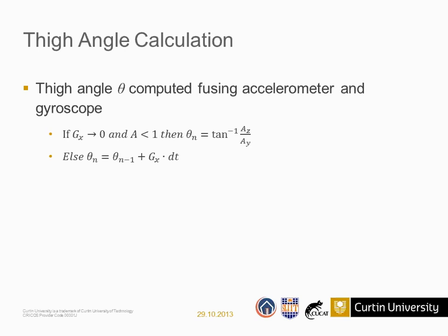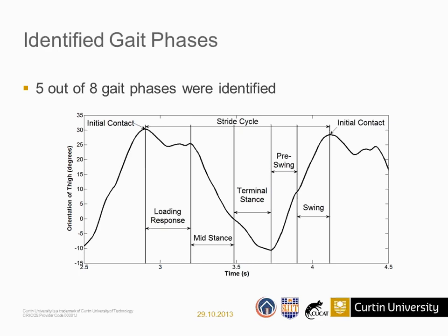So what I did was, when there is minimum motion I use the accelerometer only to get a correction. Do a correction, then keep on integrating the gyroscope, because integrating the gyroscope is more accurate than deriving the angle from the accelerometer. But it will introduce a drift. So to avoid that, whenever the motion is very small, I'm using the accelerometer to calculate the angle, do a correction and then keep on integrating.